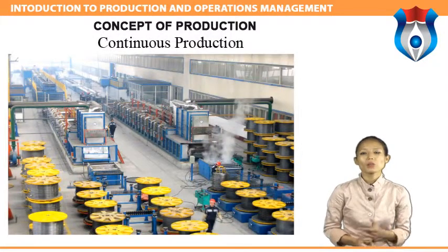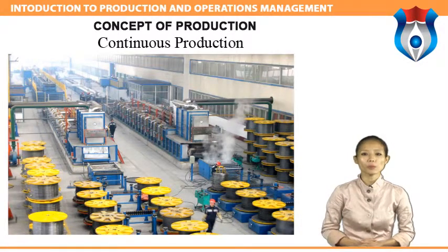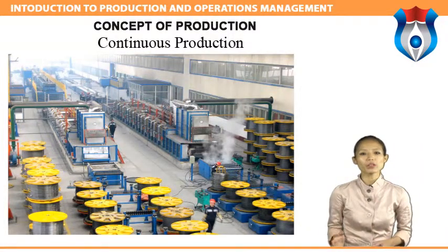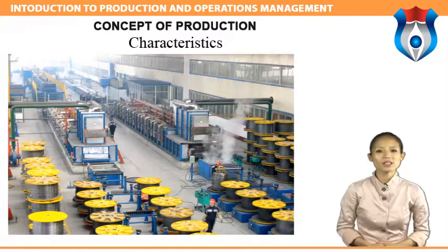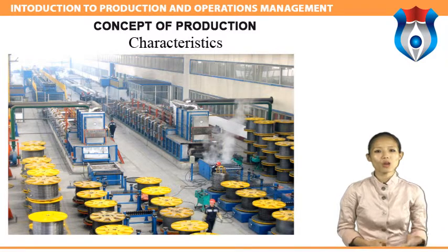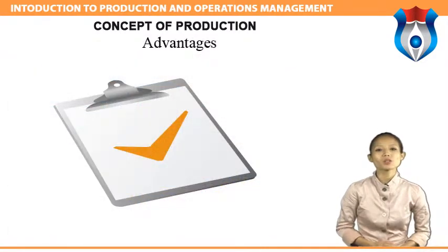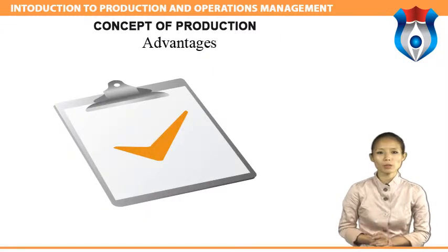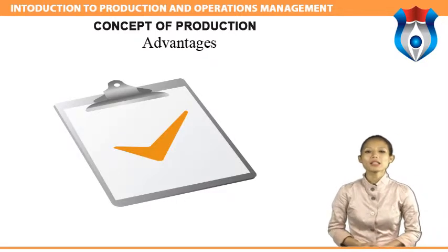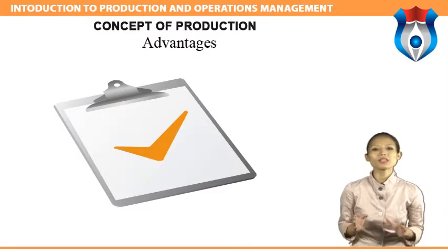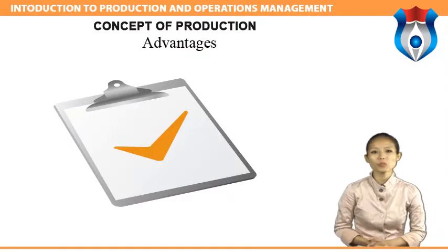Continuous production. Production facilities are arranged as per the sequence of production operations from the first operation to the finished product. The items are made to flow through the sequence of operations through material handling devices such as conveyors, transfer devices, etc. Continuous production is used under the following circumstances: dedicated plant and equipment with zero flexibility, material handling is fully automated, process follows a predetermined sequence of operations, component materials cannot be readily identified with the final product.